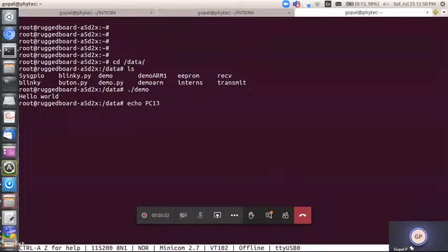It will ask you for the pin number, I need one numeric number. So here we have an ARM controller, with multiple parallel GPIO ports. The parallel ports start from PA, PB, PC, PD like this. PA goes from 0 to 31, and PB starts from 32 and so on. Each parallel port occupies 32-bit registers.